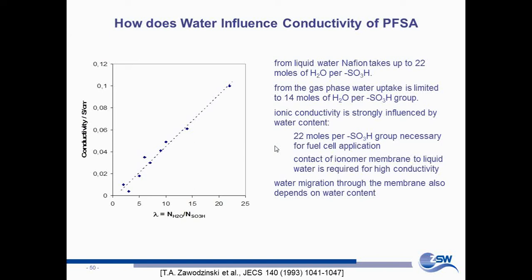The higher the temperature, the steeper and the narrower the zone between flooding, or drowning, and drying becomes, and the more elaborate you need your operating strategies, temperature-wise, flow-wise, current-wise, in your fuel cell. And from a materials point of view, if you were able to raise that broad comfort zone to higher temperatures, then this would help a lot.